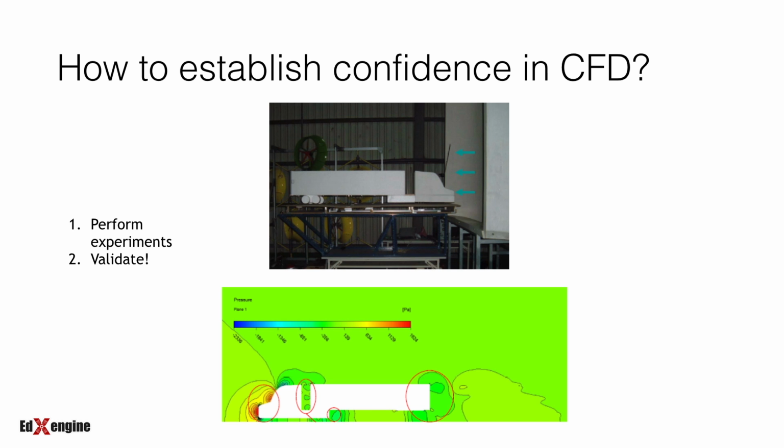This process is repeated for several different configurations to finally establish the right CFD parameters. Once a reliable CFD model is in place, the engineers can modify the geometry as required and keep running the CFD simulation. When an optimal design has been found, they can run experimental testing on that particular design alone. This is how CFD plays a role when it comes to optimizing drag coefficient.